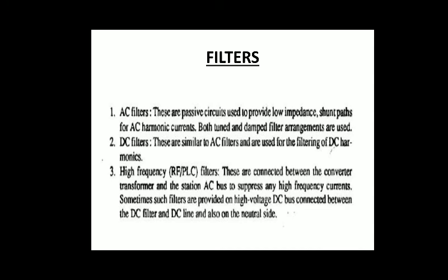So there will be a signal, like a voltage with 150 hertz frequency, within this supply, and these harmonics are bad, because of this high frequency input, the machines like generators or motors, whatever it is using, get hot. Heat is generated. In DC filters the harmonics are an undesired part of the input. So these are the differences between AC filter and DC filter.